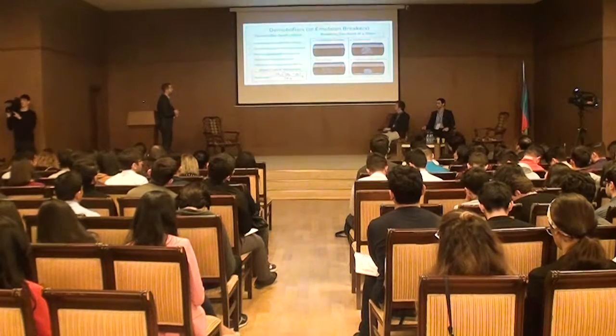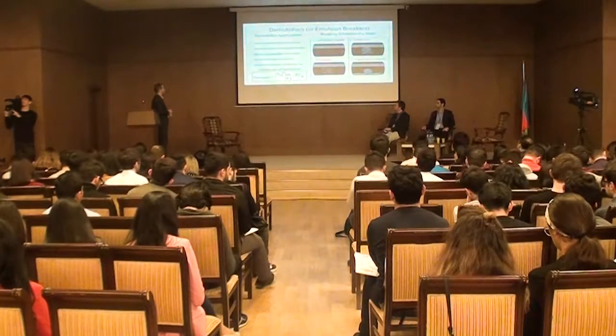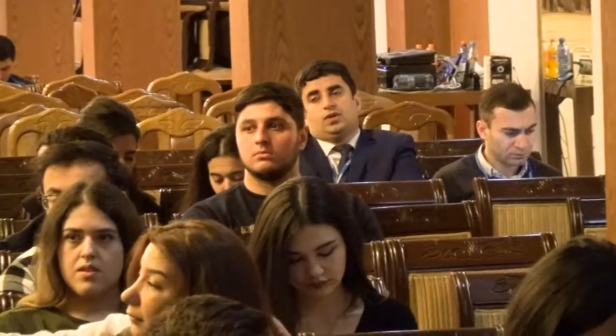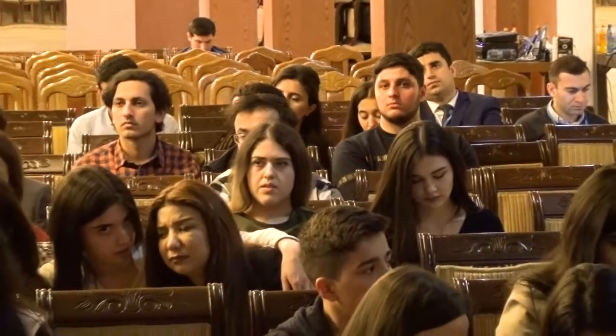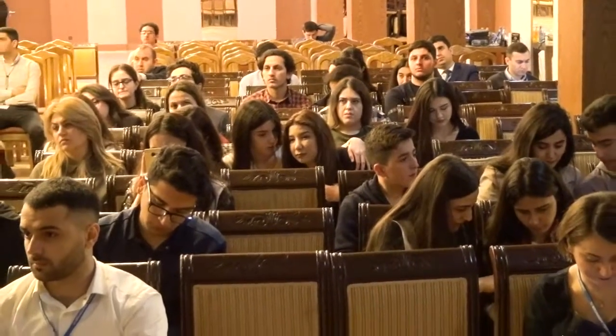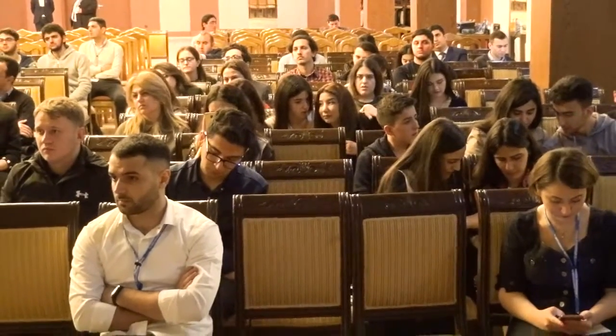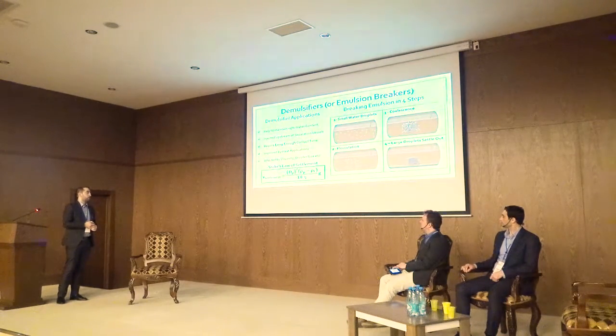We need long enough contact time of the chemical with the system to have efficient separation. And this settlement of water droplets can be explained by Stokes' law of settlement, which says that the velocity of the droplet down the system depends on the droplet size, the density difference between the droplet and the system fluid, gravitational force, and viscosity. Which means that if we increase the heat, it will reduce the viscosity and we will get good separation.